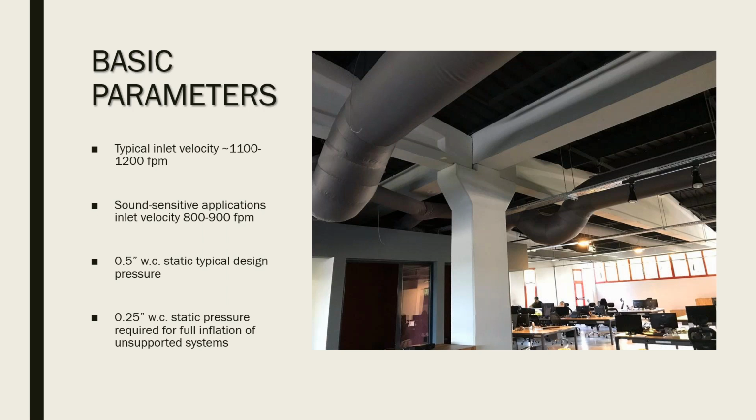At the inlet, ½ inch is typically what we design for static pressure, and you need at least a ¼ inch for the duct to remain round, especially if you don't have any type of supports.